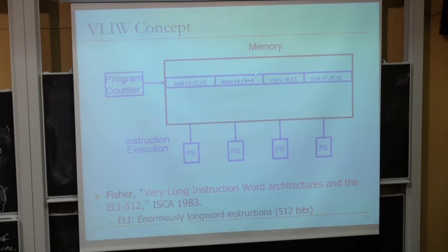The compiler doesn't put the code such that there's a load element here only, and the load is here. If that was the case, and this is a problem in the superscalar processors, you need to take the load from its location and route it to the load unit. Think about the reservation stations that we discussed. You need to distribute the instructions to the reservation stations. In VLIW, the compiler does it for you. It has to have visibility into the machine structure, which means that now you're very microarchitecture dependent. You're exposing the microarchitecture to the compiler.